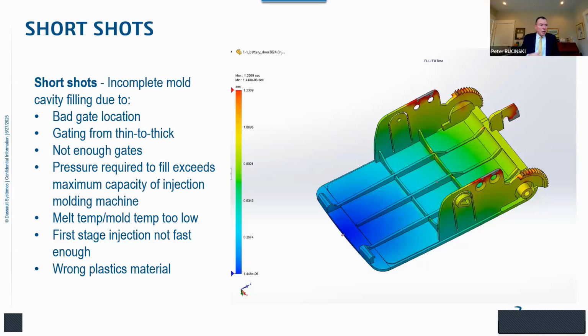So we might have to move from a higher molecular weight formulation of polypropylene to a slightly lower molecular weight that will have lower viscosity, lower resistance to flow. Now we can properly fill and pack our mold. So it's kind of amazing, just one defect here, multiple causes, often very difficult to know what the exact cause is unless you're using simulation.